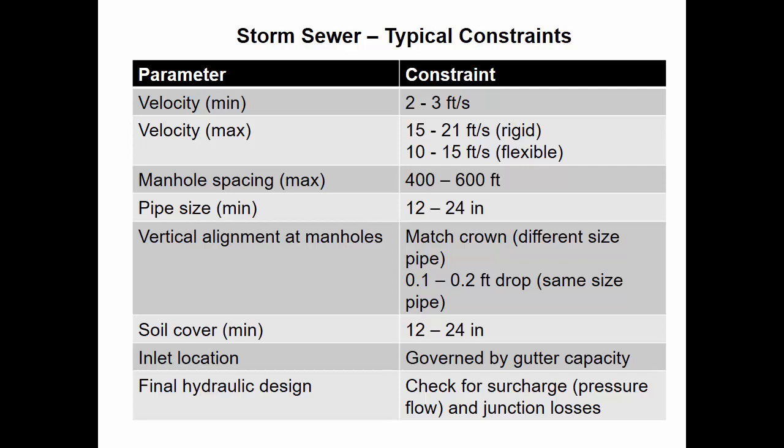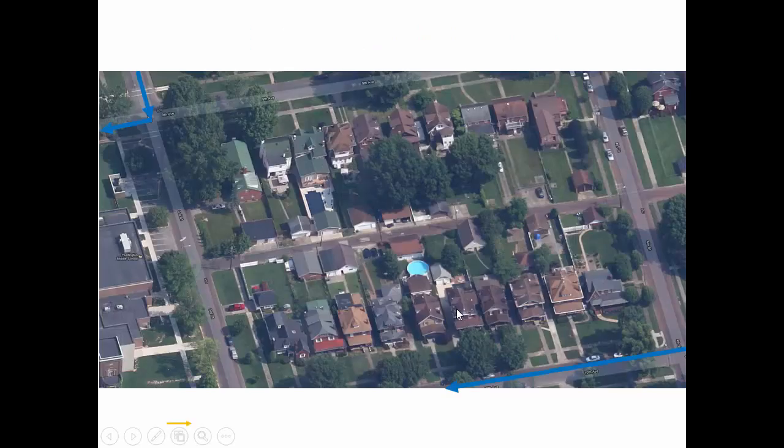How is the system going to fail? Are there going to be pipes that are under pressure, and potentially a lot of pressure? If you have a really hilly network and you've got steep pipes that are feeding into one pipe, then you have to know, well, the water's going to still be coming through those steep pipes. What's going to happen when it gets to the flat pipe? Is there going to be a manhole cover that explodes off of its foundation?